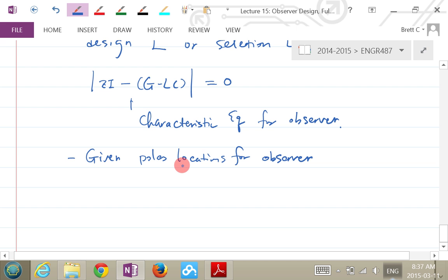Now, the pole placement location determines the whole system response. You design a K, and the system responds in a certain manner. So this pole location is for you to do the estimation, so that the x hat of k will catch up with the actual x of k. This pole location determines how fast x hat catches up with x of k.